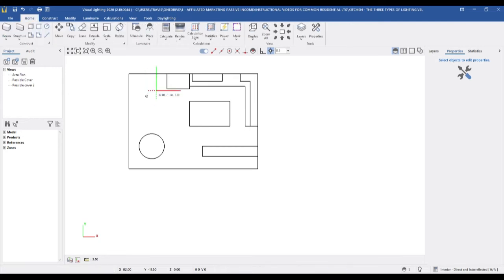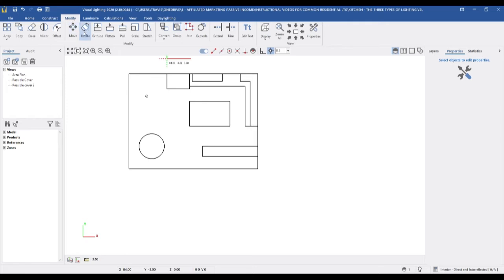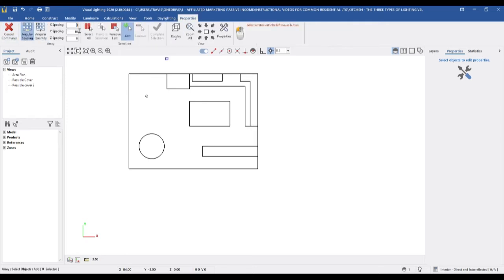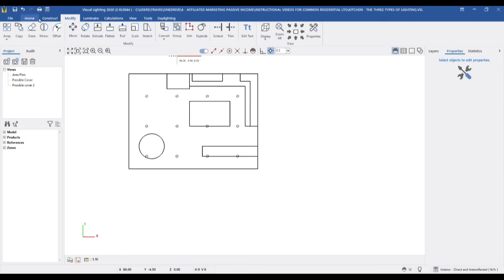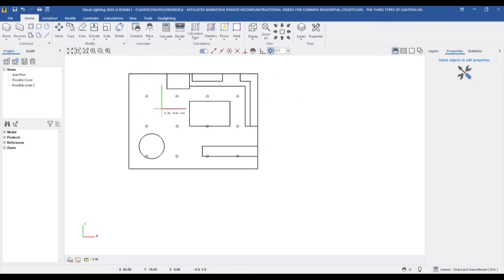Now all this applies only to the ambient lighting filling the space. We want to create an even amount of light so it's easy on our eyes and the brain, because large contrasts will make it difficult for us to focus, give us headaches, and our eyes will have a hard time adjusting, especially to large contrasts. So the goal here is even light with minimal glare.